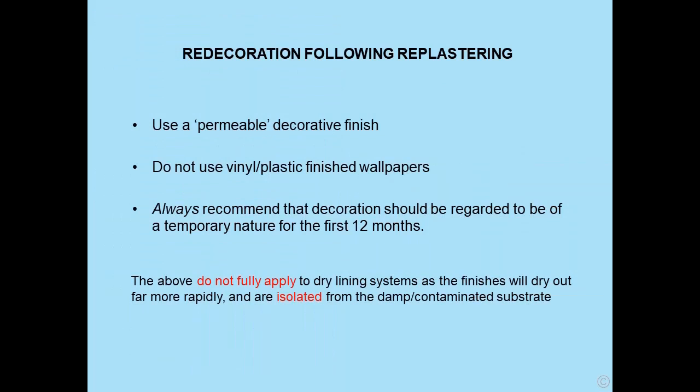What about redecoration? Well, this really applies to sand cement mixes, wet mixes. Use a permeable decorative finish. Do not use vinyl or plastic finish wallpapers. These can give problems. But just as importantly, always recommend that the decoration should be regarded to be of a temporary nature for the first 12 months.